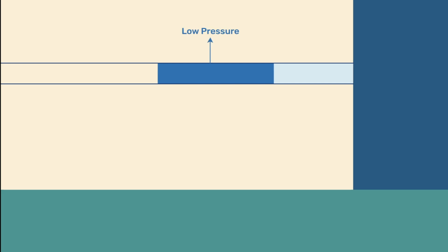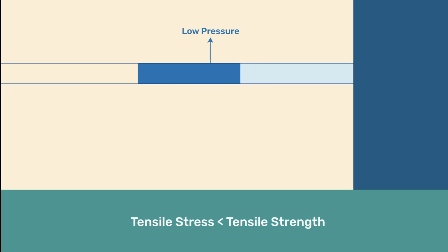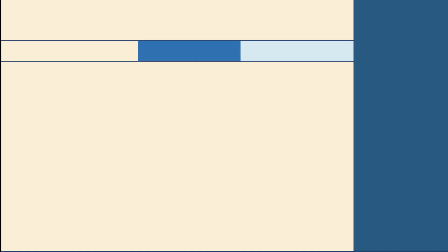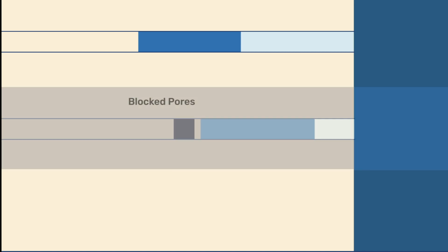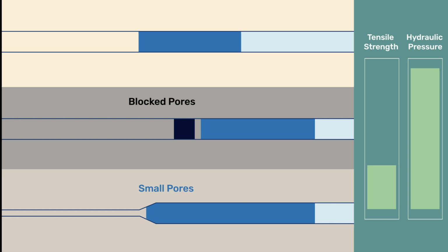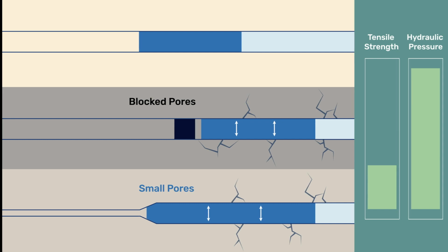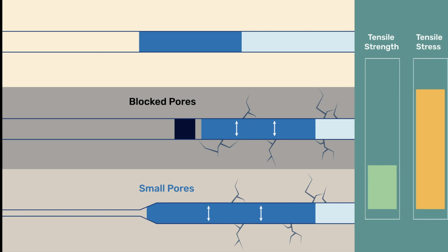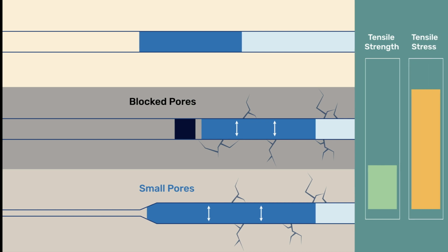In such cases, the tensile stress felt by the material may remain below its tensile strength so that damage does not happen. However, if the water cannot flow freely enough as the ice advances, for example owing to hydrophobic treatments, blocked pores, or very small pore sizes, then hydraulic pressure builds up in the liquid, causing it to push out against the solid matrix so that damage becomes increasingly probable and cracking is expected when the tensile stress in the porous matrix exceeds the tensile strength of the material.